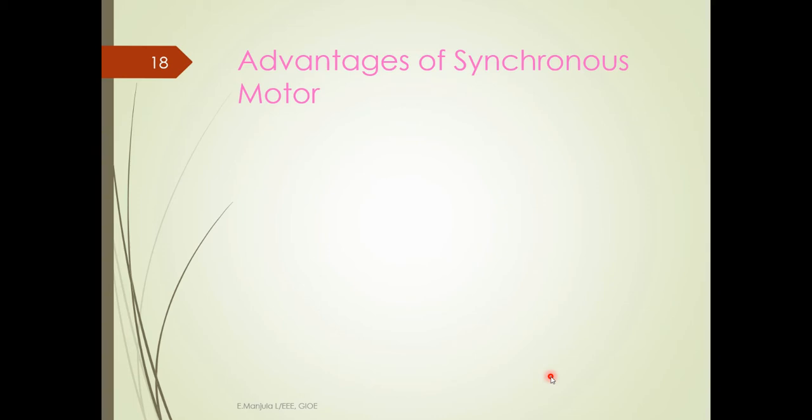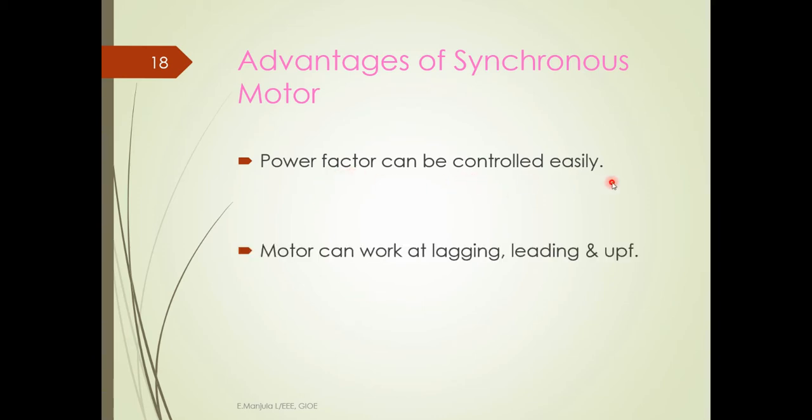So what are the advantages of the synchronous motor? Here, the power factor can be controlled easily and the motor can work at lagging power factor, leading power factor, and unity power factor. And speed is constant and it is independent of load. Though you have put a lot of load on a synchronous motor, the speed of a synchronous motor is constant. It does not change like an induction motor.